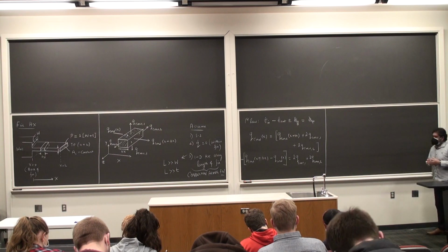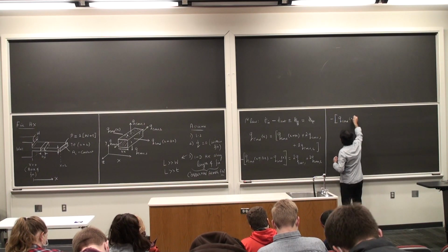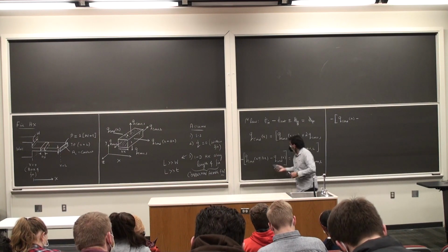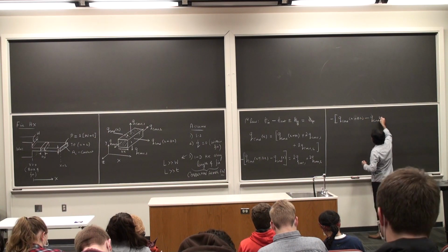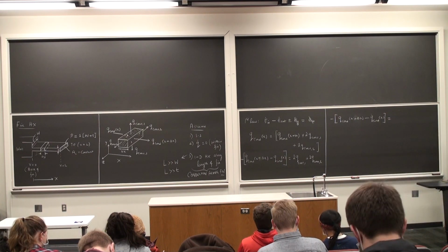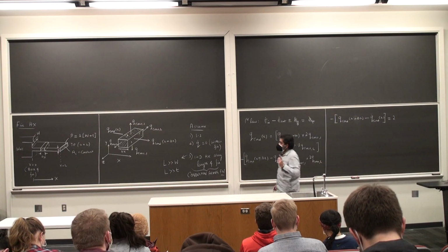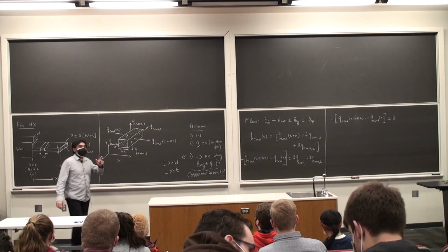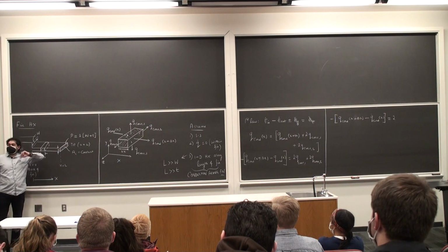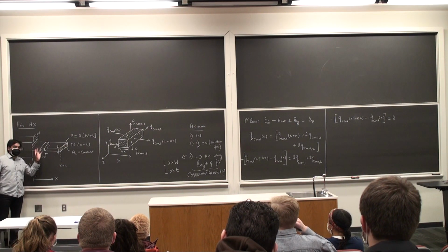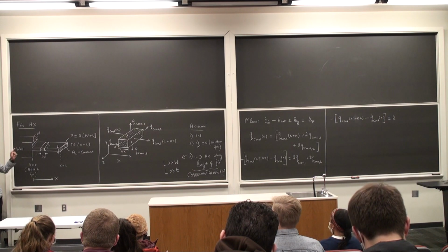Then I start expanding Q convection 1 and Q convection 2. So minus Q conduction x plus delta x minus Q conduction x, that is going to be the following. Watch this carefully. 2 times, big assumption, the convective heat transfer coefficient, I'm going to assume, is the same between the top surface of the fin and the ambient, the side surface of the fin and the ambient, and the tip of the fin and the ambient. We have not reached the tip of the fin yet. I'm looking at the interior of the fin right now, and at all the other regions that are exposed to ambient. This is a big approximation. It's not really true. But we should continue.